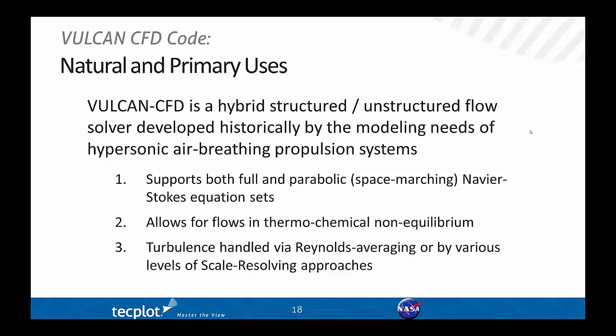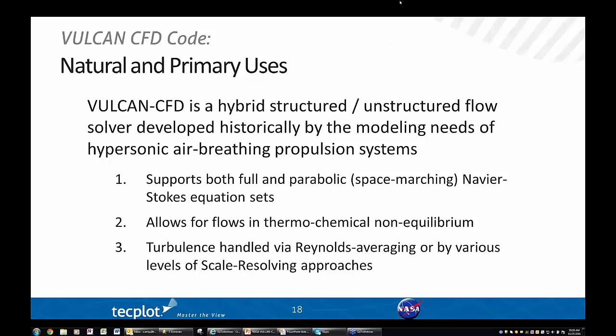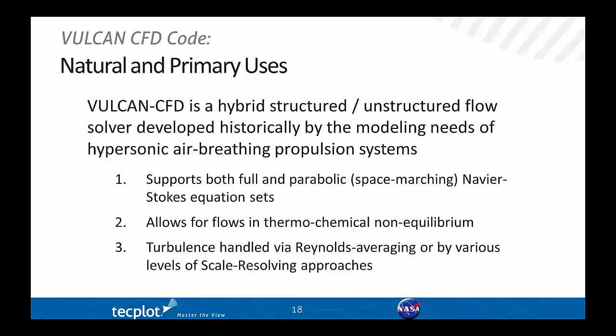And finally, as far as turbulence modeling, most users of the code use the software in a Reynolds-averaged framework using standard Reynolds-averaged models. But we do have a whole suite of scale-resolving simulation strategies that you can choose from as well, for large eddy simulation or hybrid RANS/LES simulations.